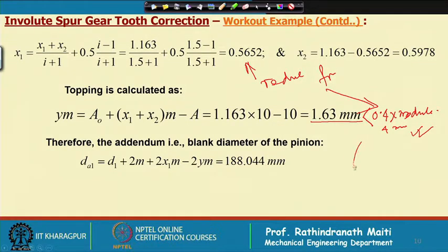In that case, we can truncate this one, say instead of making it like this, we can make the teeth up to this one, say in that case this height above the working pitch circle may be 0.8 into module, that is also acceptable, say close to stub teeth, and for that possibly it will come like this and we can verify the center distance. However, at instant we can accept this one. Okay.